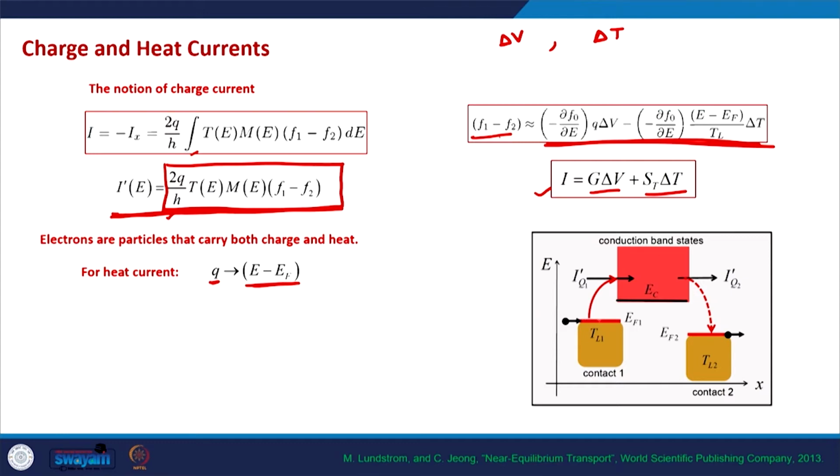A new electron entering the metal enters at the Fermi level, or any electron exiting leaves from the Fermi level itself. Even in a semiconductor, the Fermi level defines in a way the distribution of particles in the material. So, in order to define heat current, the amount of energy in excess of the Fermi level, E minus EF, is the heat in that system.